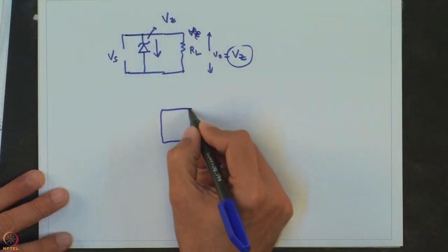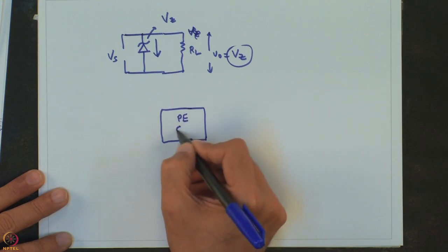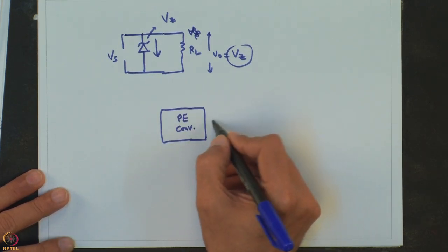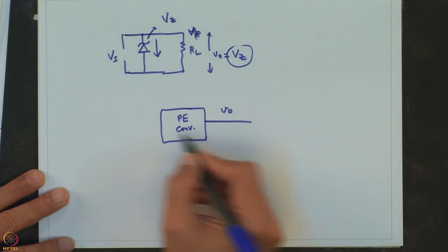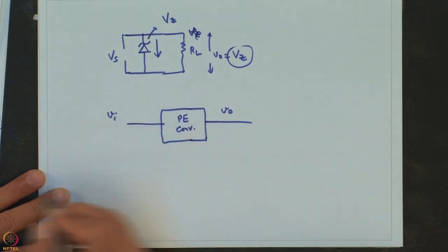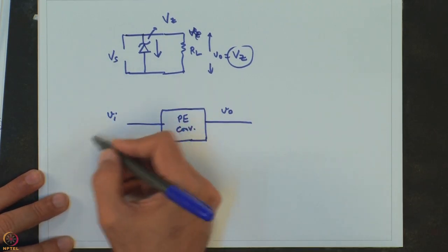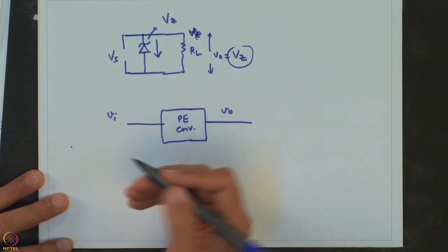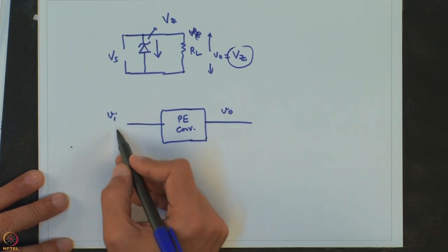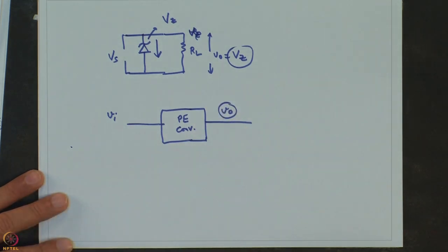So, when we say a voltage regulation problem, I will just quickly draw again my PE converter or the PV circuit, and let us say this is the output voltage VO, and there is an input voltage Vi. Now, this could actually be obtained either from a direct DC source or it may be coming after rectification from an AC voltage which may be subject to variation. And I told you that if the AC voltage will vary, the Vi would vary, which we are applying to the P converter, and so the output voltage VO will vary as well.